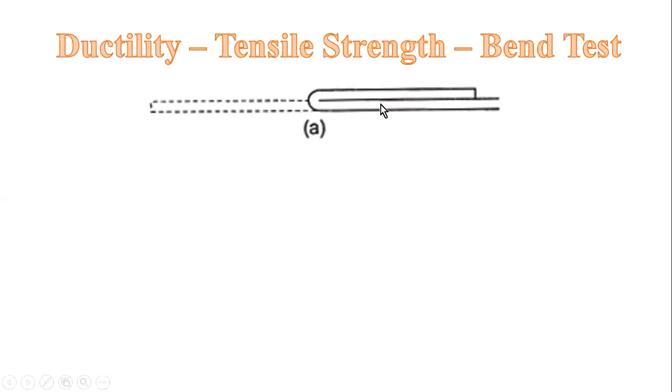This is a bend test. And this is a closed bend test, in which the specimen is bent over on itself and flattened. As you can see, there is no allowance made for spring back, and the material is satisfactory if the test can be completed without the metal tearing or fracturing. So if you don't see any fracturing in here, you will have a metal that is approved for a closed bend test.